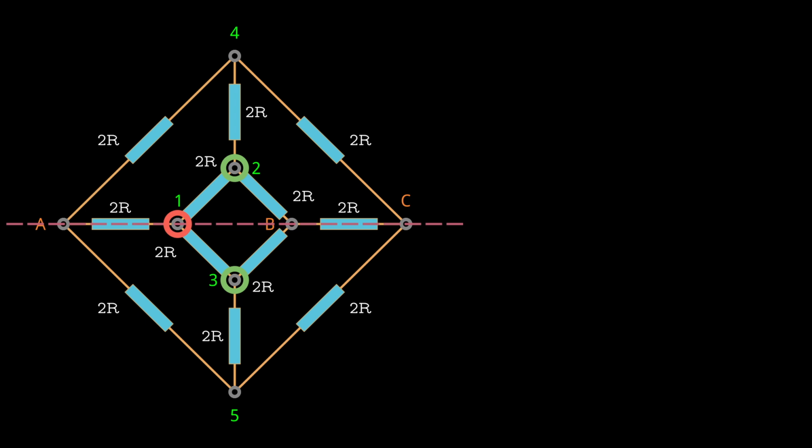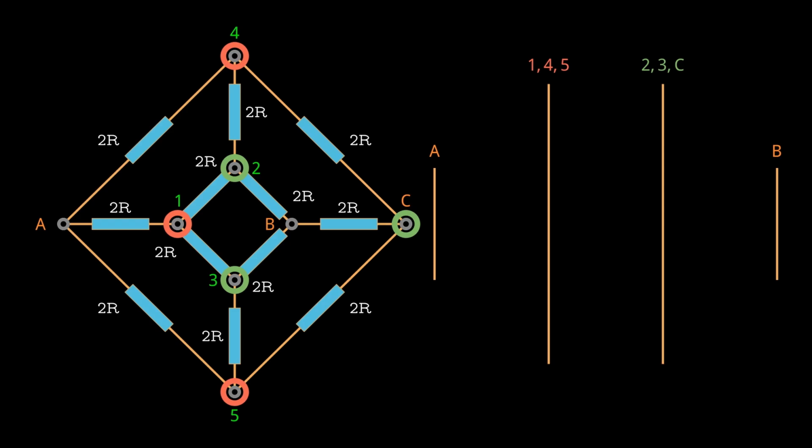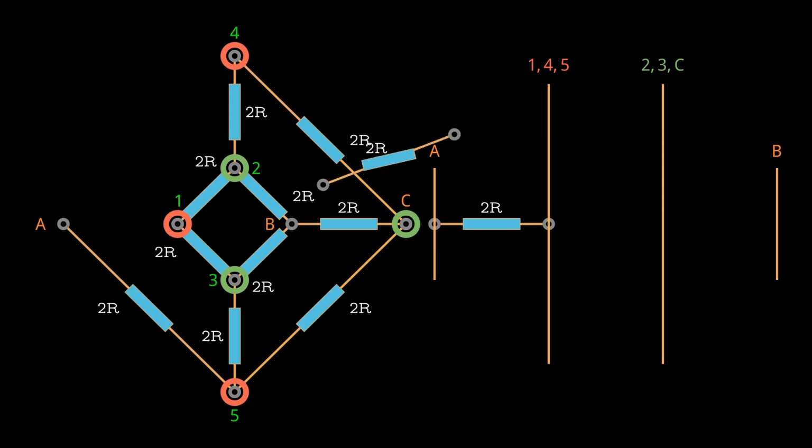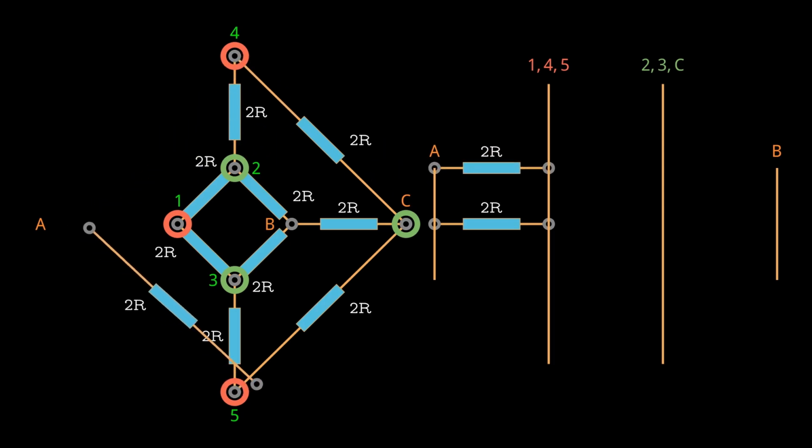To make these equipotential nodes easier to identify, let's mark nodes with the same potential in one color. As it stands, identifying series and parallel resistors here can be challenging, so let's redraw the circuit for a clearer view. First, identify the two nodes, between which we're finding the equivalent resistance. Next, draw lines marking the equipotential nodes, and then place each resistor carefully between these lines, one at a time. You'll want to do this patiently, ensuring no resistor is left out.